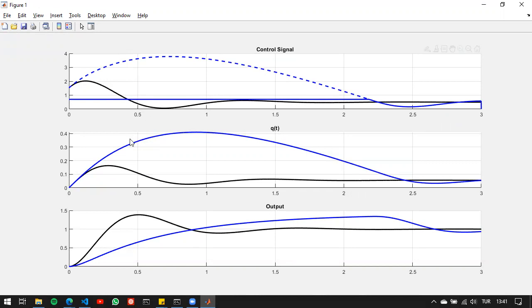Here, the integrator is basically messing up the behavior. The controller cannot perform well because the integral part grew too much. And it again takes some time to decrease and get rid of this huge sum that is accumulated in the integrator here.